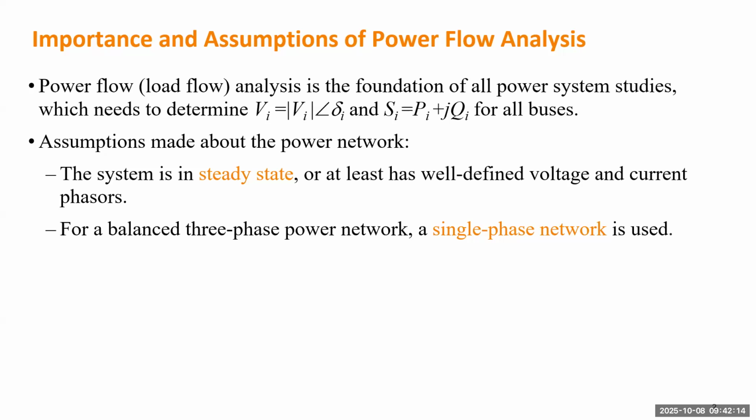So you can still use power flow analysis on each sequence network, for the positive, negative, or zero. They will give you some indication about what the post-fault system can be. Even if it's maybe not 100% accurate, it's still very useful. It's very, very quick, much faster than simulating the 3-phase network at a very tiny time step, right? Which means power flow analysis can be applied to many studies, not just steady state and balanced conditions. But definitely if the system is in steady state and the network is perfectly balanced, the power flow result will be very accurate.